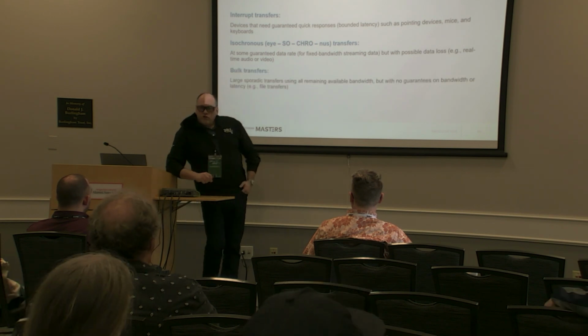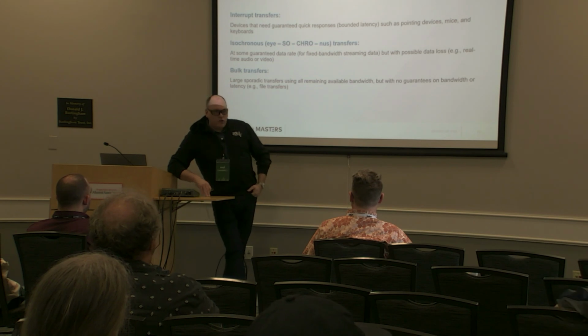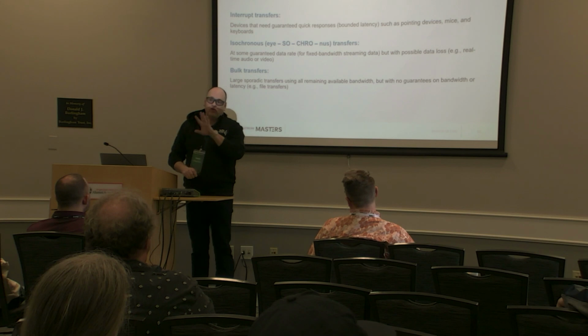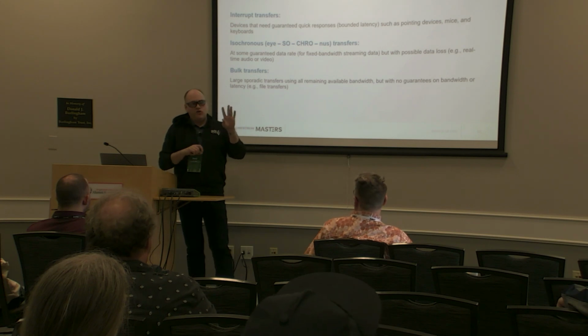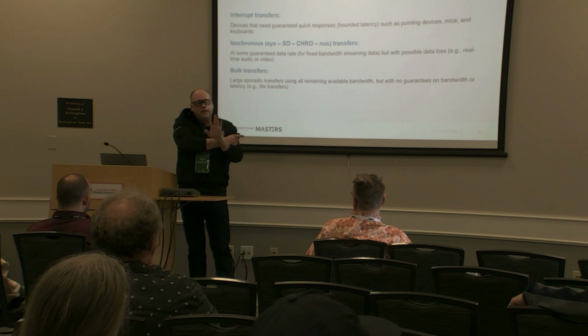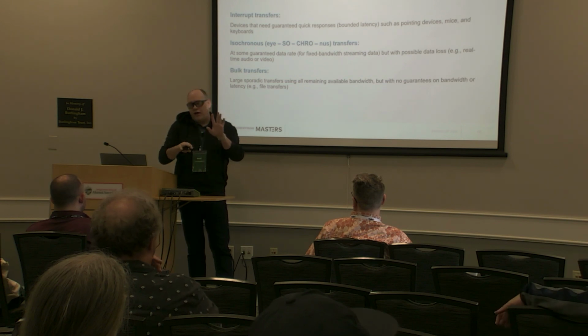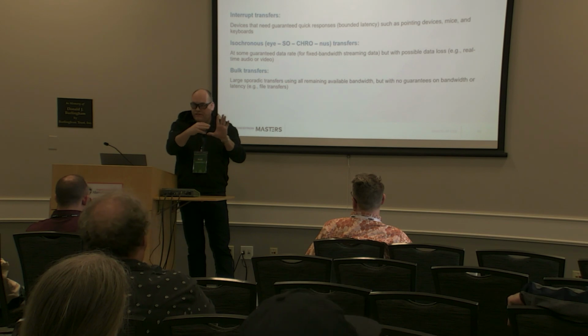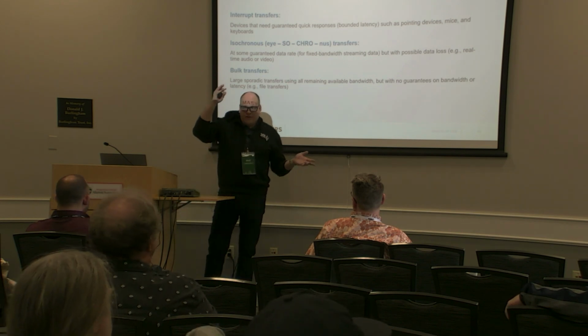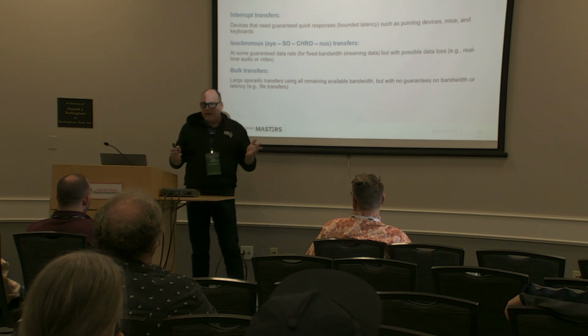The next type is bulk transfer. That's your file transfer. That's your external hard drives. It will take whatever's left. So if you have an isochronous stream going and you plug in a hard drive and try to copy something from that device onto your desktop, it's not going to impact that stream because of the way it's enumerated. It can't interrupt that feed, right? So don't think that because you kill that file transfer, it's interrupting my video call. That's not what's happening, right?